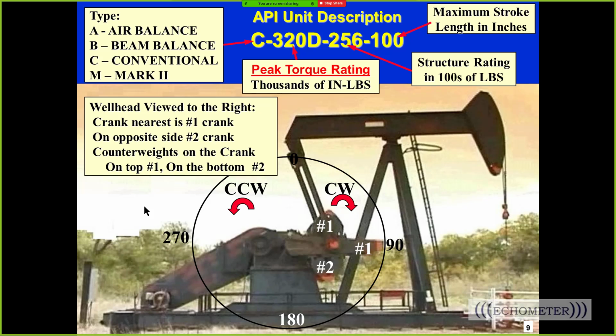You're going to be able to use that data to determine where the weights need to be placed without knowing the geometry of the pumping unit. So it's a very simple, quick and easy device to use, and you don't need to know the geometry of the pumping unit or where the weights are. But it's also very nice to know what weights and cranks are on the pumping unit, because I like to compare the net torque from the gearbox mechanical calculation to the torque calculated from the power probes, and they typically should match.